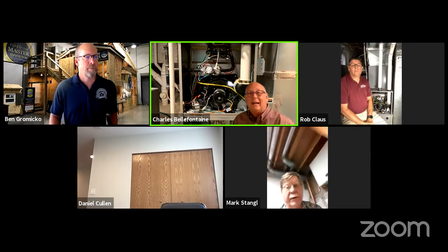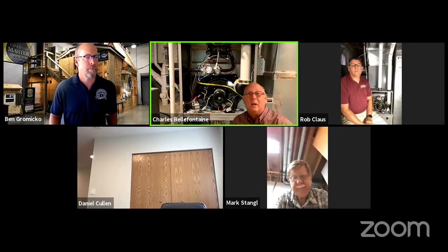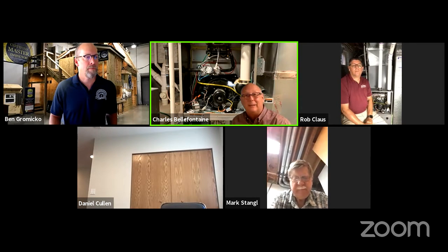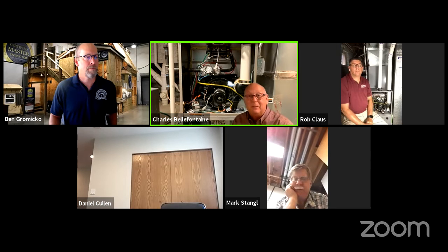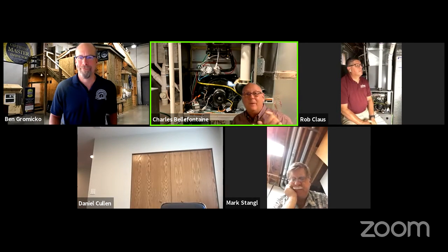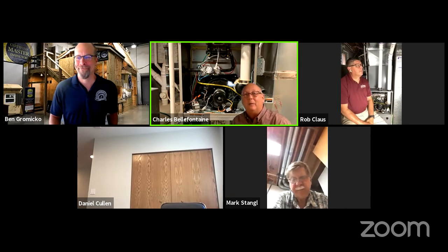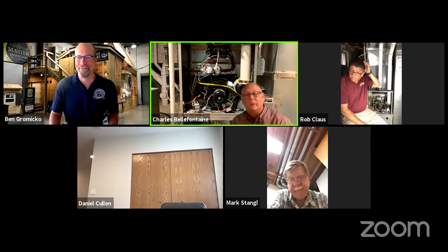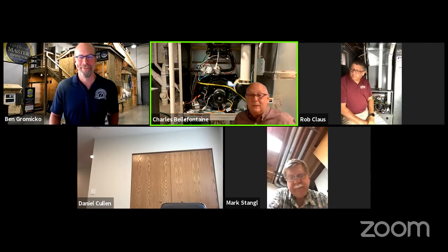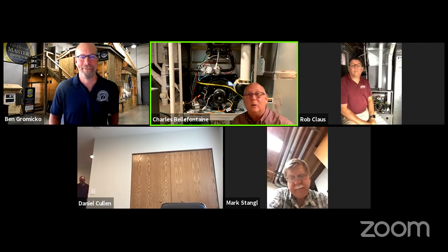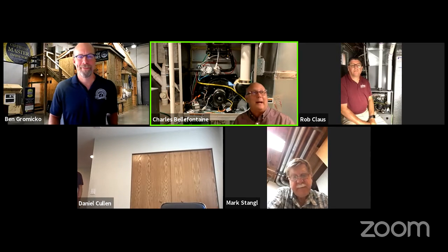That condensation is very caustic. It's one of the reasons why we have to use plastic pipes and not metal pipes, because if somebody did try to put a metal pipe on this, and I have seen it once, that condensation will eat through that in about a year or two. Usually by the time we get there, it's already eaten through, and then you're dumping carbon monoxide straight into the house. Obviously, that's a problem, so it needs to be plastic.